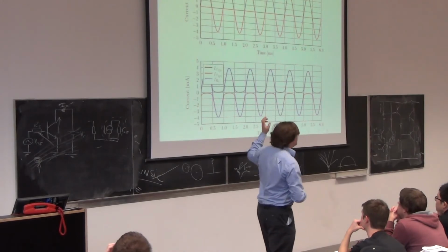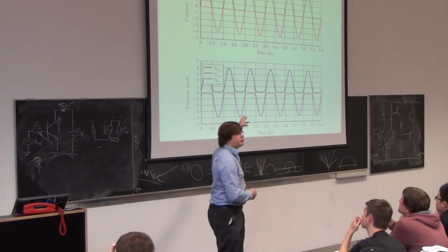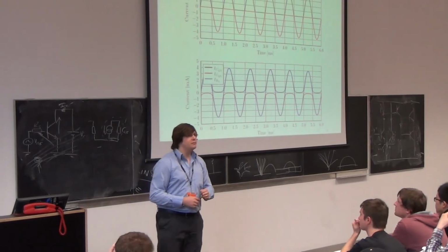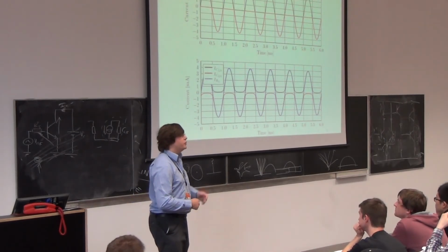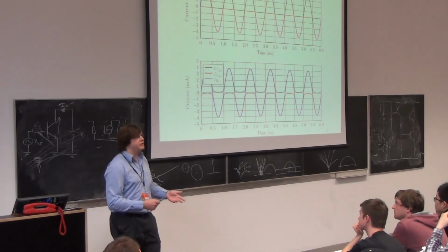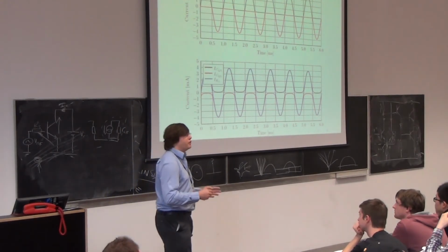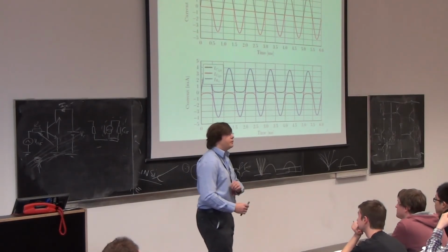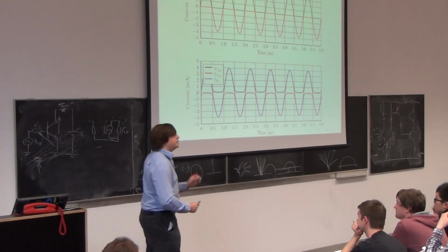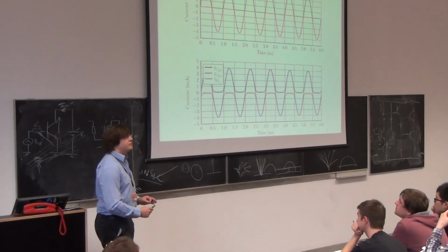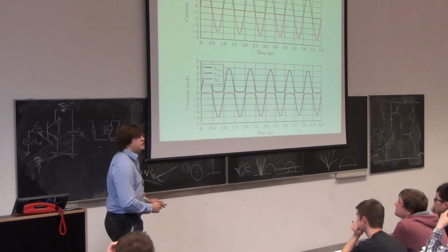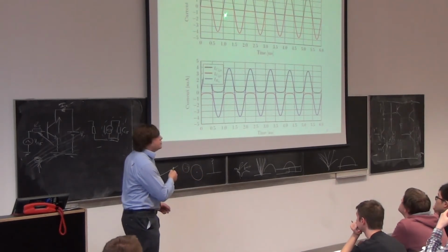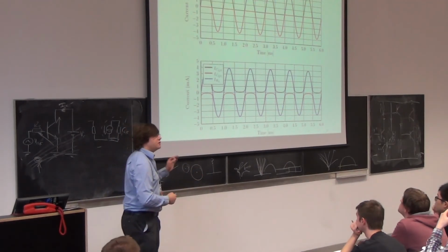If we had lots and lots of data, took a Fourier transform and looked at the frequencies that exist, we would find there is some non-linearity in the circuit. We put in 1 kilohertz, we'll get out 1K, 3K, 5K, and the components of the 3K and the 5K and so on will be small, but they will be there. Very difficult to get rid of them completely. Very difficult to totally eliminate crossover distortion. But we can say the angle of conduction is almost 180 degrees, assuming that I've trimmed it just right.